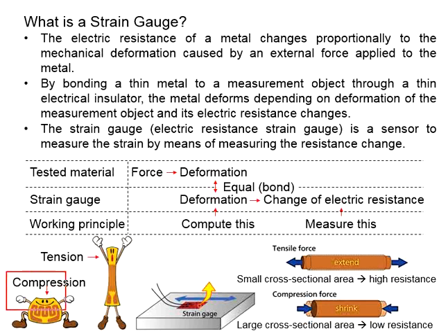Now, if the strain gauge is undergoing compression, the wire becomes shorter and fatter. The resistance reduces. By quantifying the reduction in the electric resistance, knowing the proportional relationship with the mechanical deformations, you are able to quantify the strain also. This is the context of the strain gauge.